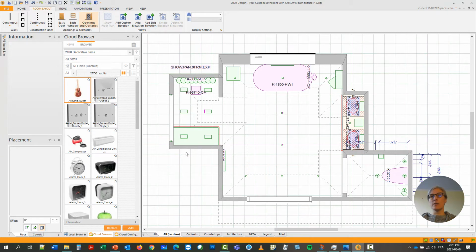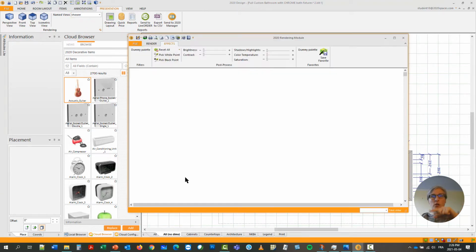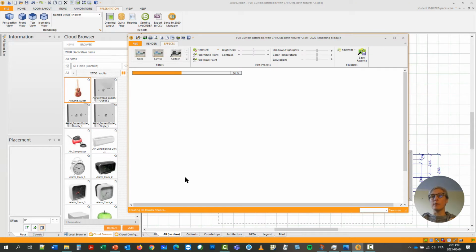And because I want to center it towards this wall, I will right click on the cutout, choose Center, and double click inside the placement zone of that wall. Double click. Now I have my cutout perfectly placed. Let me go inside the shower and I will show you how the texture is wrapping up around.